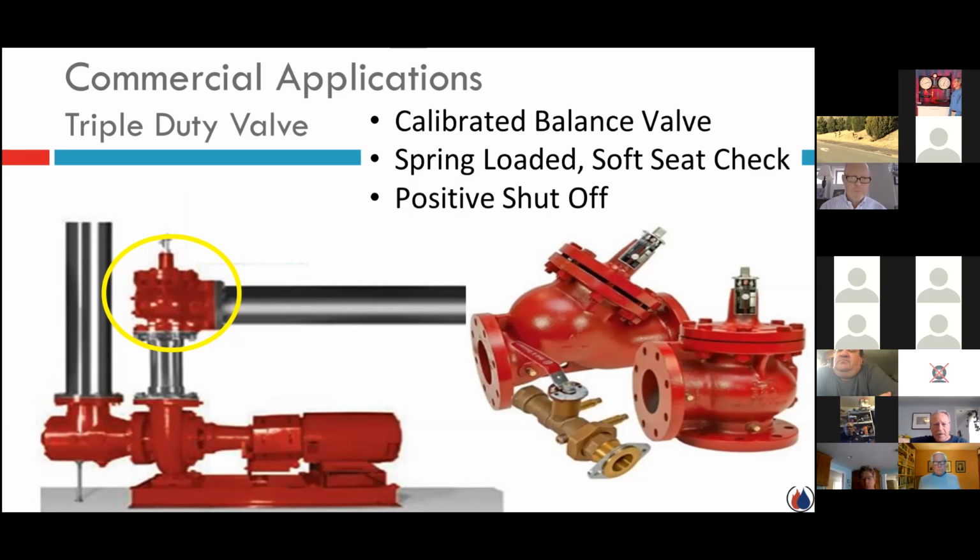It's around, over the years, one of its popular applications that actually, as energy codes are starting to change, might lose some of its flavor, had to do with when a pump got spec'd, so the design conditions were originally established. Sometimes there'd be what you could refer to as a CYA, cover your tail. So they'd maybe put a little more head energy, a little higher head than was necessary.